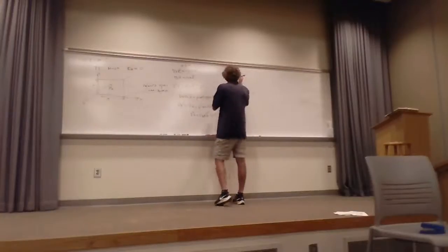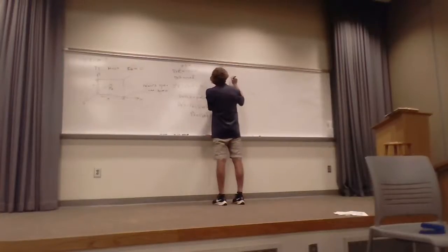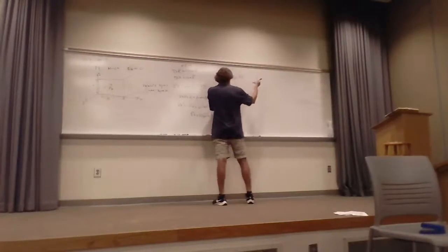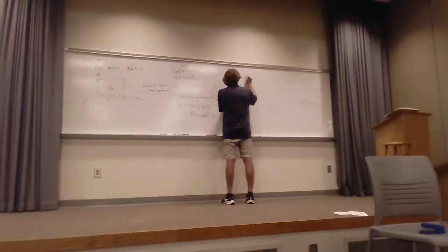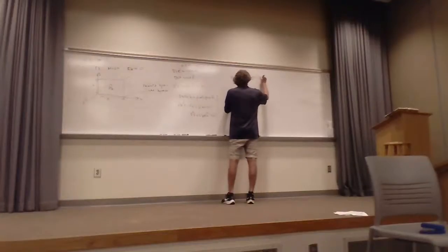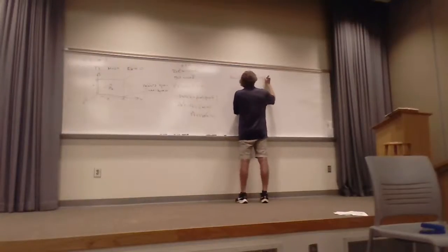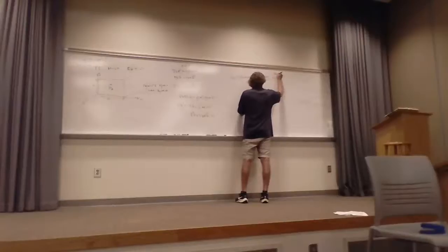And we come up with, when we apply the boundary conditions, Hz is equal to some H0, some scalar value, times cosine of m pi over a times x, and not sine, cosine of n pi over b times y times e to the minus j beta z times z.